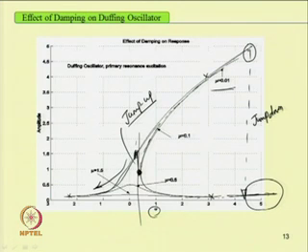So, here also this will be a critical point, after which we have only a single solution. Up to this frequency we have multiple solutions, and after it we have a single solution. In this way, we know that at a bifurcation point either the stability of the system changes, or the number of solutions or responses changes. So, either qualitatively or quantitatively, the stability and the response change at bifurcation points.